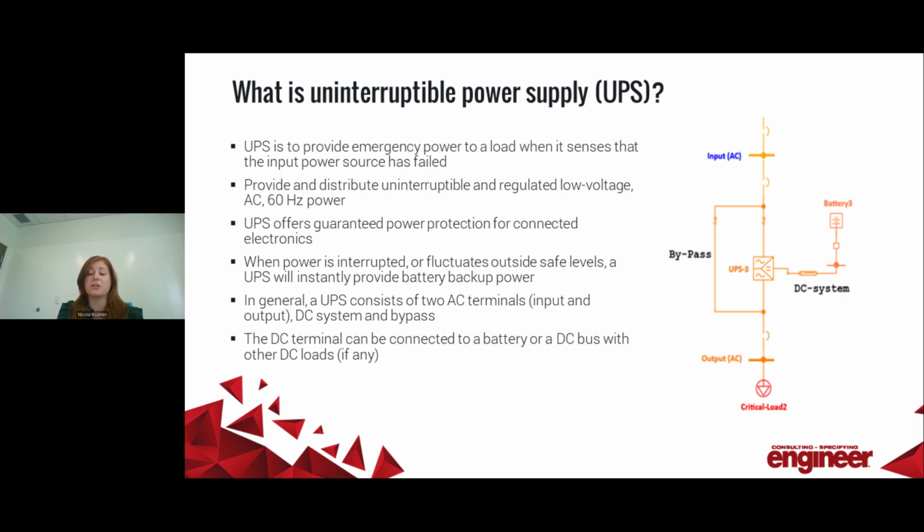The output voltage is determined by how long those switches are closed, and the frequency of the output is determined by the timing of the pulses. This is typical for a pulse width modulated inverter. There are also ferroresonant inverters, but they are pretty much obsolete. And I think the last time I tried to specify one, I could only find one vendor that still made them. Inverters also use filter techniques and controls to meet time, current, and voltage characteristics that you set for their output, regulating frequency, voltage, and wave shape.